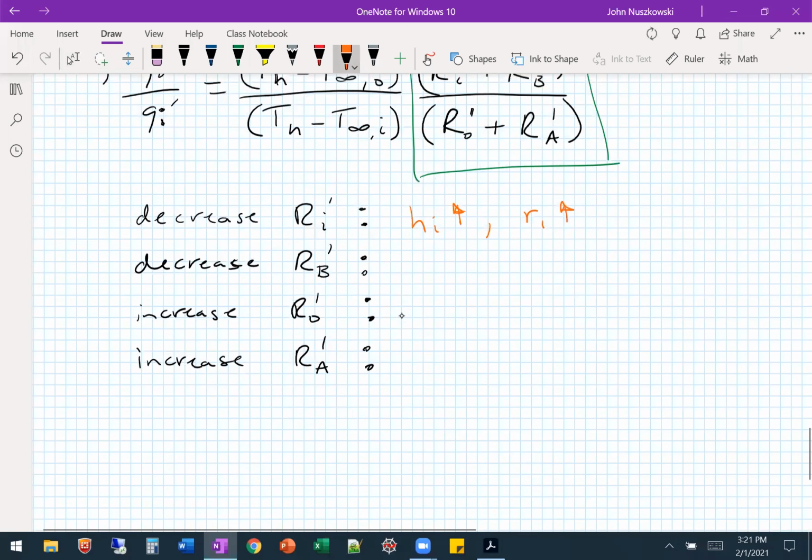And there's also, looking at the natural log, you want to do R2 over R1, you want to decrease that ratio, okay? So that's KB, higher thermal conductivity materials. So aluminum, copper, something higher in thermal conductivity would help us.